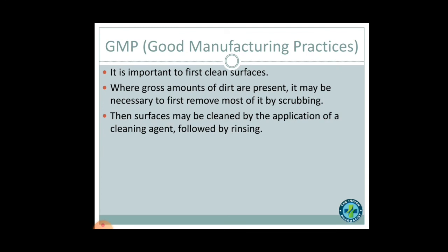It is important to first clean surfaces. The surfaces which come into contact with the product should be kept clean. Where gross amounts of dirt are present, it may be necessary to first remove most of it by scrubbing. If required, scrubbing is allowed, but it should be done with a soft cloth or nylon brushes.